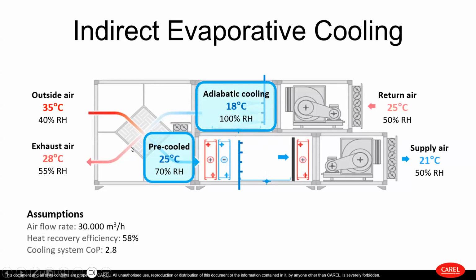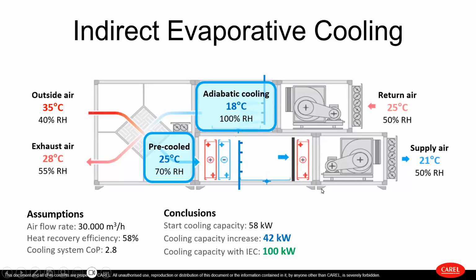The heat exchanger can cool down the incoming air from outside without exchanging humidity. So you have cooling thanks to the waste air coming from the unit. And you can supply air with really small mechanical cooling, which means that you increase the efficiency, lowering the operating cost and also the carbon footprint.